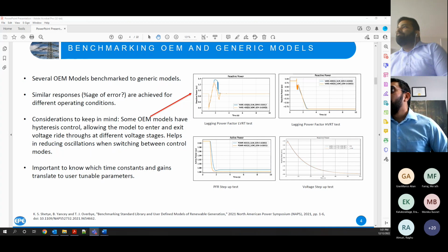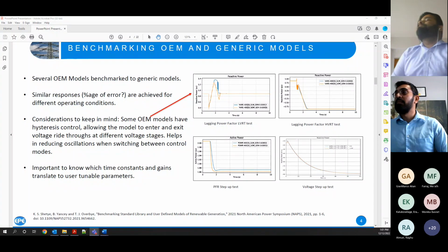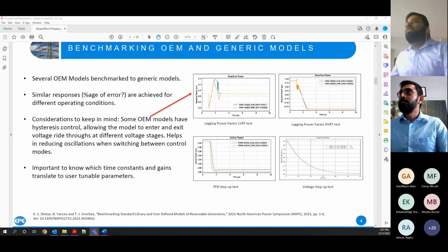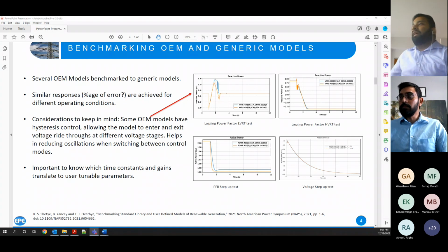Is the master plant BU1 model plus the REX4 BU1 suitable for controlling a solar plus BESS hybrid facility where the net injection at the POI is limited to the solar megawatts, or the plant megawatt injection output is more than the solar megawatts, but less than the summation of the solar plus BESS MVA ratings? Yeah, I get what Amrit is trying to say. Okay, so the answer is yes and no. Yes, if you're allowed to change the model parameters, because then you can limit the megawatt injection from both the facilities, either the solar or the BESS.